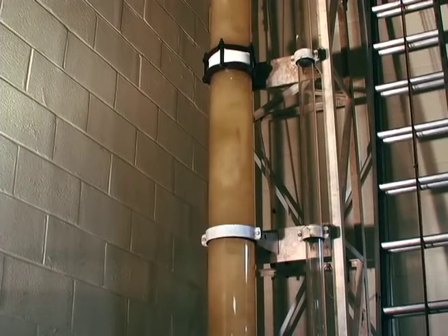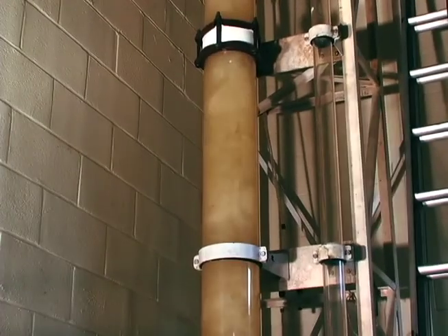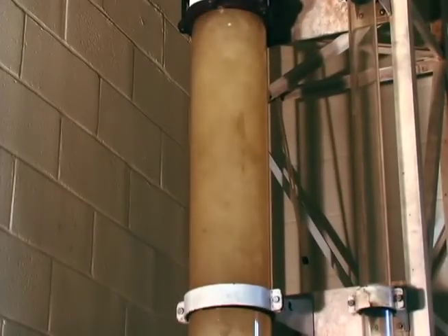The gas rate has only been increased to 8 MCF per day, and you'll notice a remarkable change. This is no longer bubble flow, this is a churn flow. This is the flow regime that predominates until the gas rate becomes quite large indeed. In a pipe of this diameter, the flow rate would have to exceed 3 million standard cubic feet per day before the churn flow would convert to something like an annular flow.